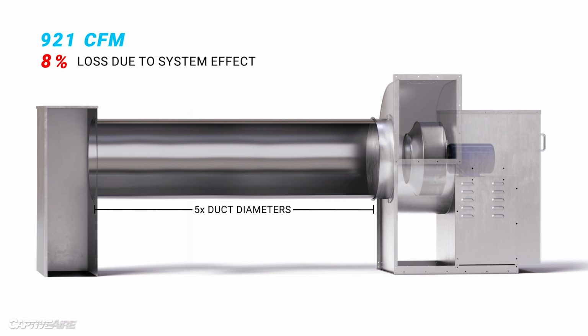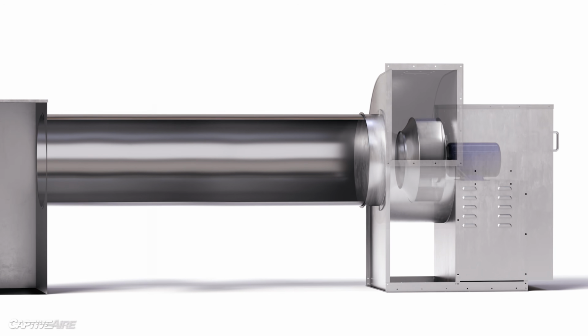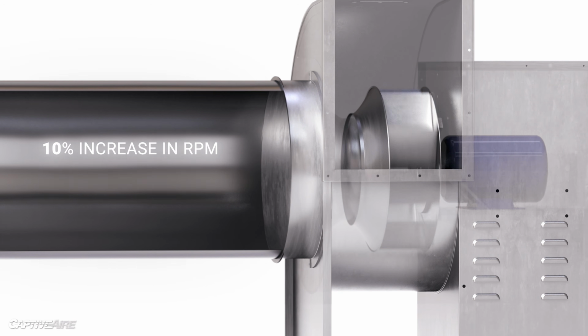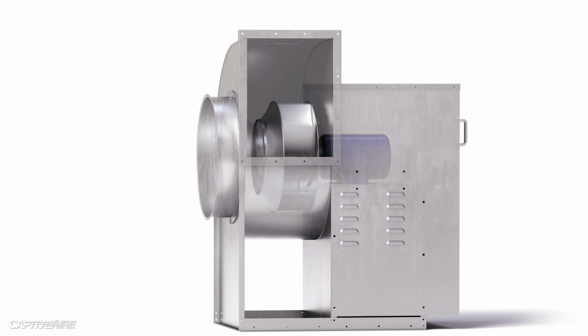But then the question is, if you have this much room, why use a square inlet box in the first place? Cost savings, maybe? Remember though, if you have to speed up the fan to make up for system effect, the fan laws tell us that for a 10% increase in speed, the fan will consume 33% more power. So is that worth it? Almost always the answer is no.